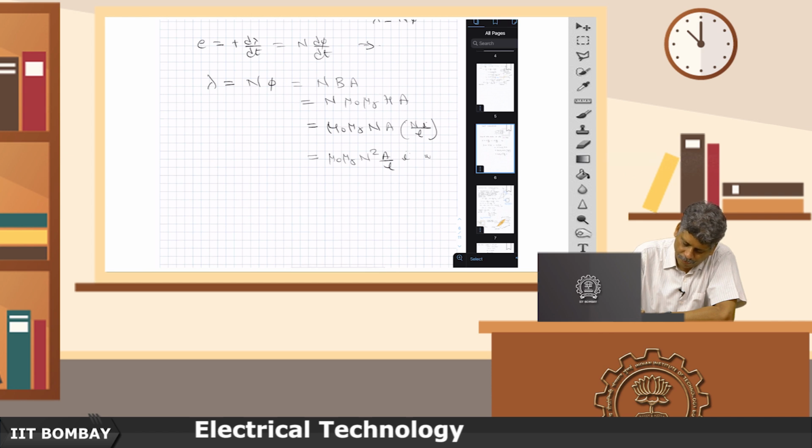and again strictly speaking flux linkage unit is Webers only, but because we multiply number of turns times flux, to indicate it in our writing, we prefer to write it as Weber turns. Now, if you look at this, it just depends upon the magnetic material, number of turns of the coil and the geometry. The A by L ratio depends upon the geometry.